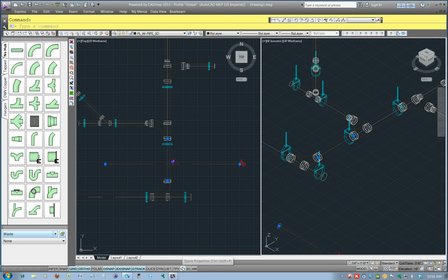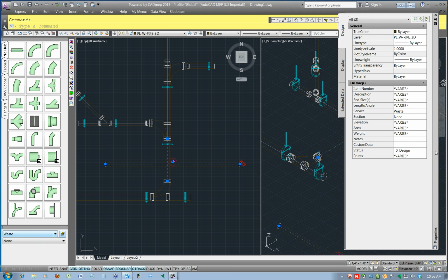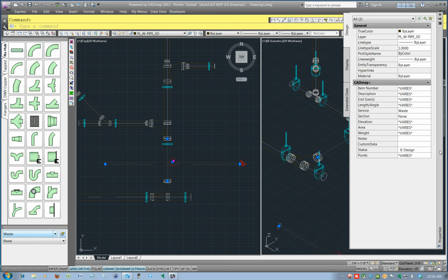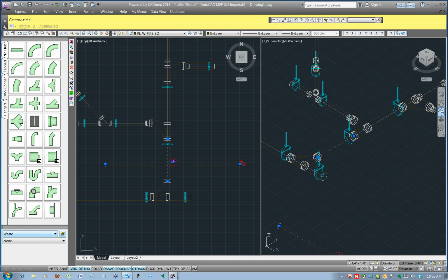Where do you see it at? Where is it normally at? It's usually right down here. Wherever you move your mouse, it'll show your coordinate. It's one of those options down there. If you select one of them, you should see in your properties the elevation. Yeah, if you just hover your mouse over. Right. The center line is 8.2. Center line, yeah, okay, that's good enough. So we'll raise the center line of this pipe to 8.2, which should be at 0.